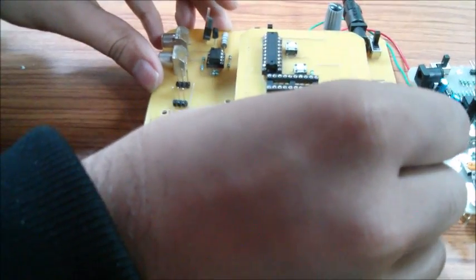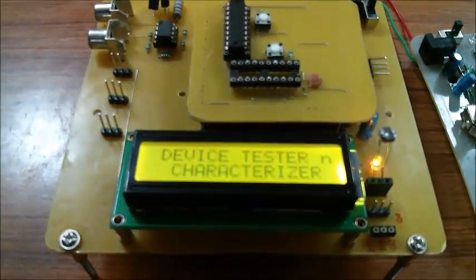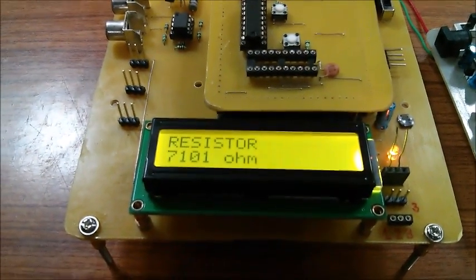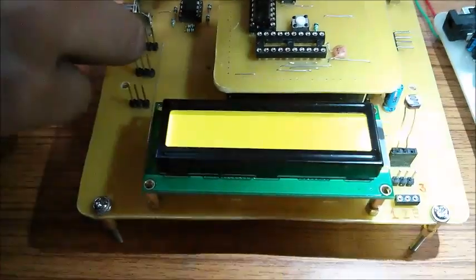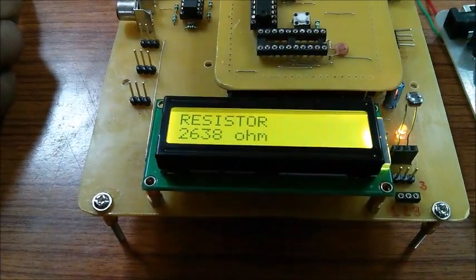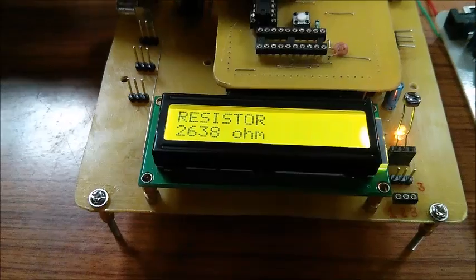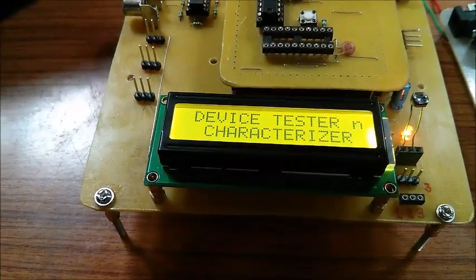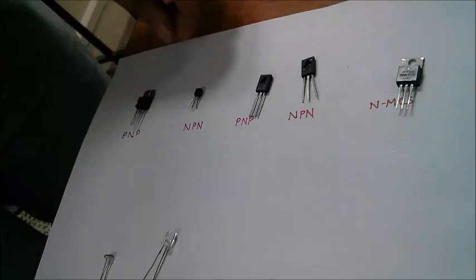Now to show the robustness of our system, we'll demonstrate the device tester with LDR as the DUT. Just like earlier DUTs, we have placed the LDR in any fashion and measure its resistance under different light intensities. Under ambient light condition, its resistance turns out to be around 7K. Now placing a flashlight over it, its resistance decreases, which now becomes 2.6K. Now we will observe the LDR under low light condition and by creating a shade over it. Now its resistance become around 10.6K.